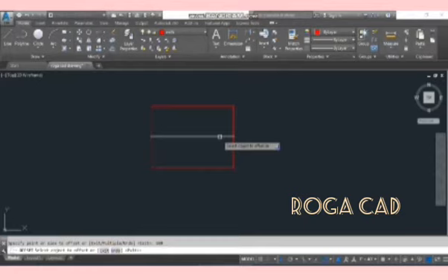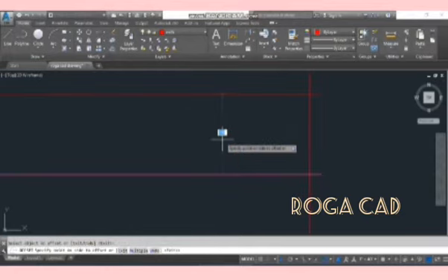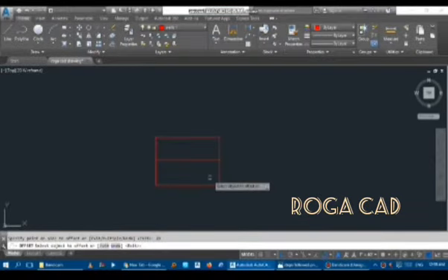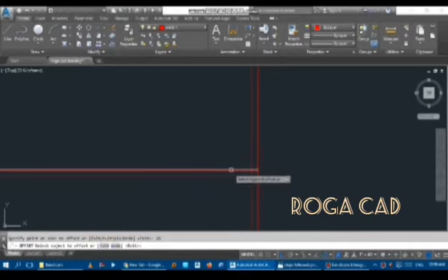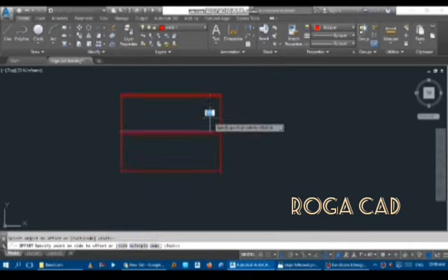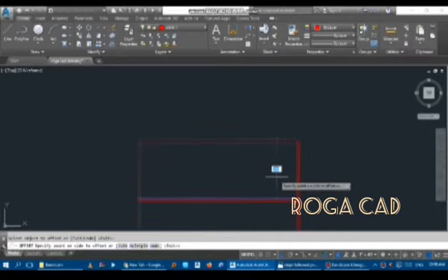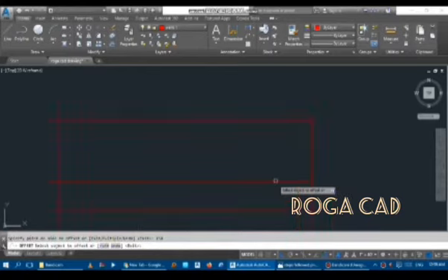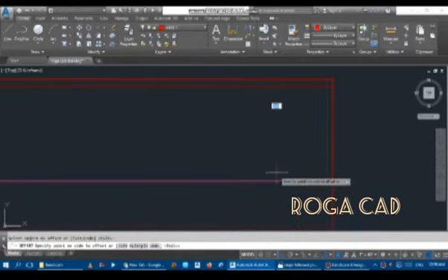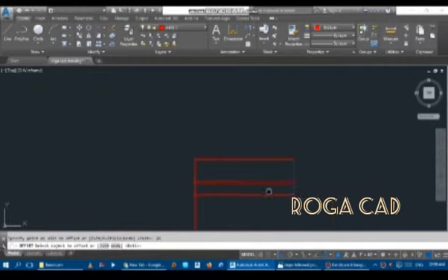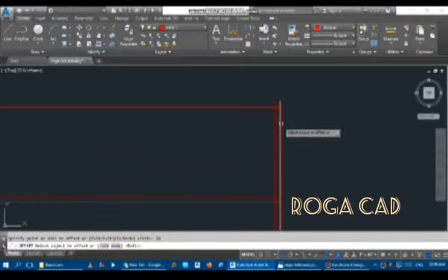And then after, we're going to create the thickness of this wall, which is 20. So we are going to proceed with our corridor, which is located here, and this will be done by offsetting this to 150 centimeters from this wall, staying in the offset command. Then we offset it by 20 to give it wall thickness, and you observe this is our corridor. Then we are going to proceed to make partitions of our rooms.